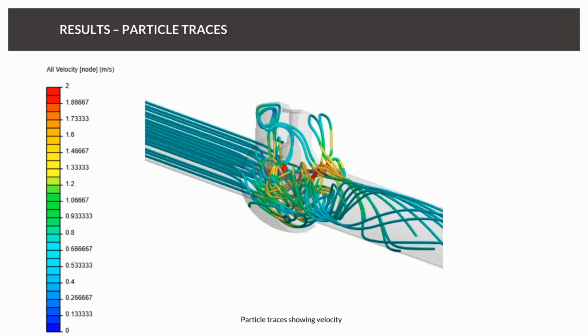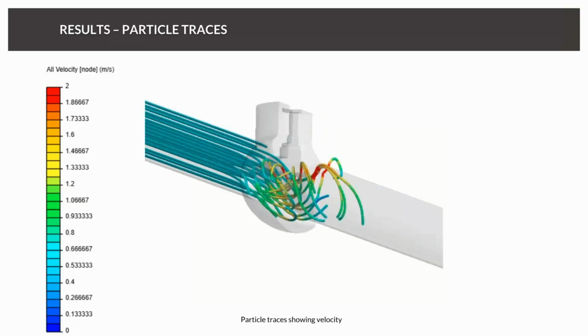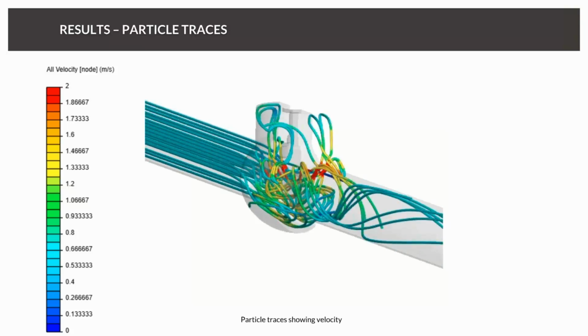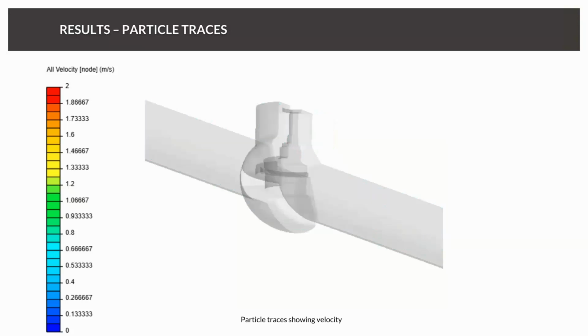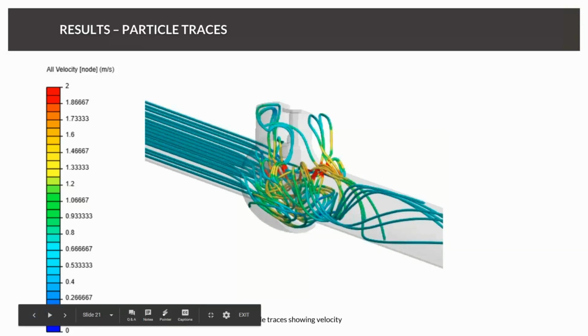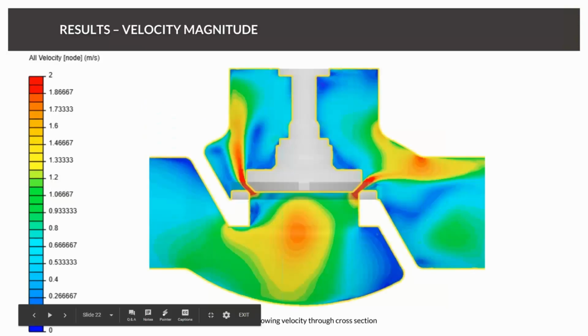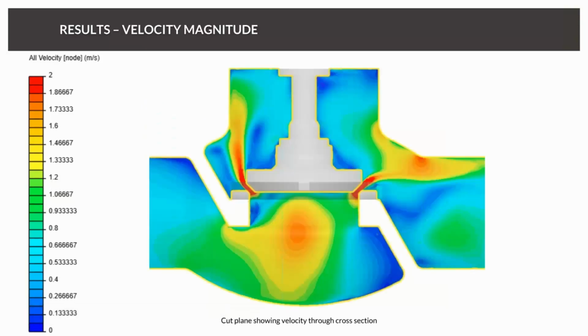I will note it is important to have an outlet extension, because you see these particle tracers are going a bunch of different directions. You don't want a lot of swirl over your outlet pressure boundary condition because you'll run into mass balance problems, and then your solution won't be numerically stable and it'll diverge. So if nothing else, just add enough that you can let the flow straighten out. So here's just velocity through those channels.